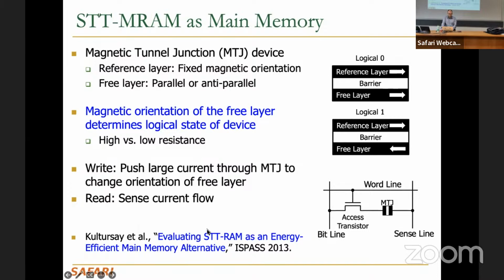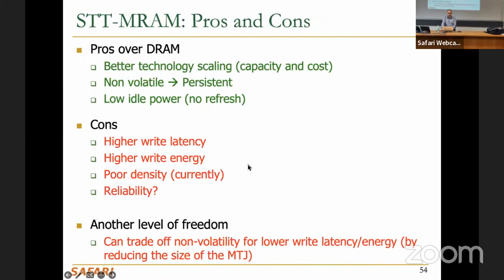If you want to learn more about STT-MRAM, you can check this paper. People have looked into using STT-MRAM instead of SRAM as well, because the latencies of STT-MRAM are much better than DRAM, but they are not better than SRAM. But at the same time, the problem with STT-MRAM is density.